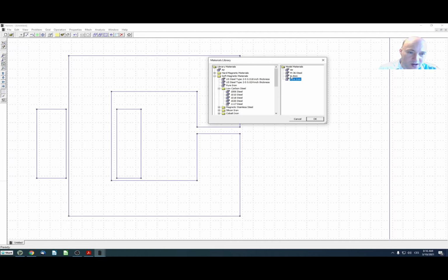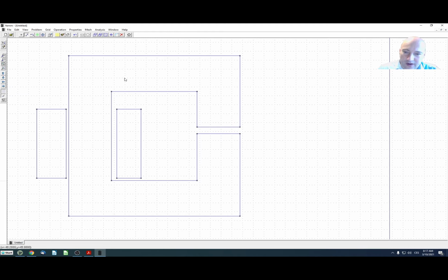So now in our model we have added those 4 materials. We now need to define those materials for our areas here. So here we use this button, which is to operate on block labels, and we will define the block of my material. So I will have one material, for example, here, one material will be there, a third material will be there, but this will be copper, so it will be the same, and here everything else will be air.